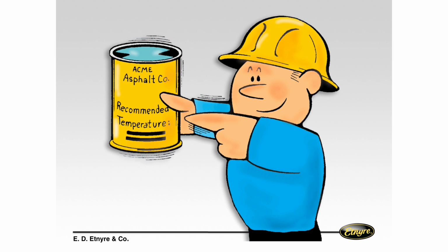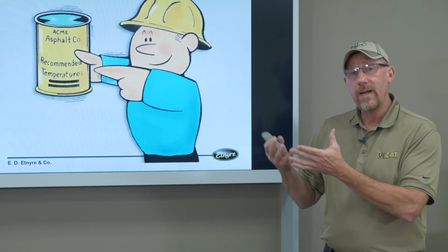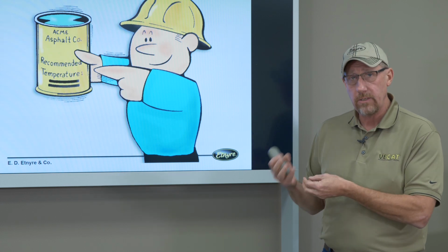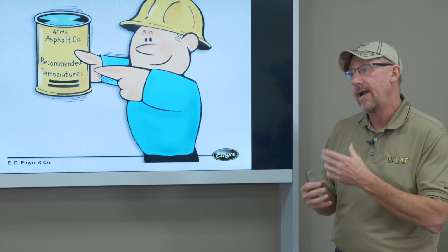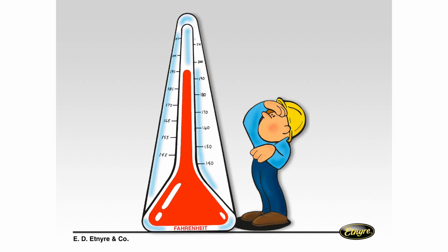That asphalt is hard that's floating around in that water. All distributor manufacturers use a gear pump. So the warmer we can make that tack, the easier it is to pump, the easier it is to circulate, the easier it is to clean the system out. So we want to take the recommended temperature and keep it up at its highest level.